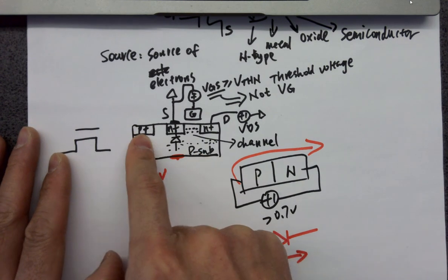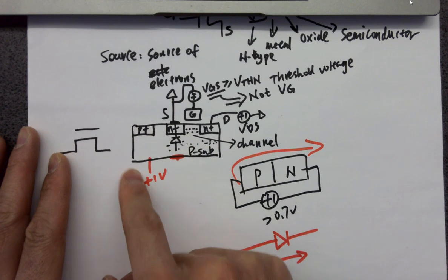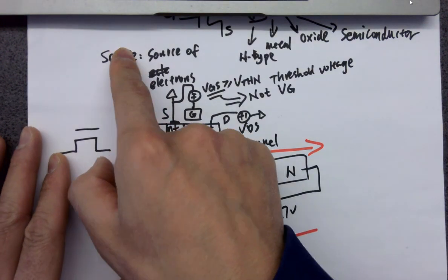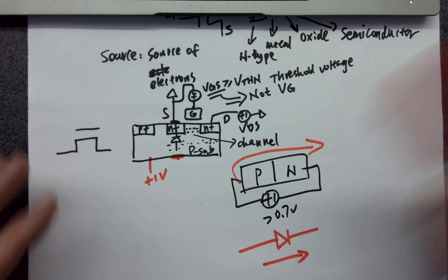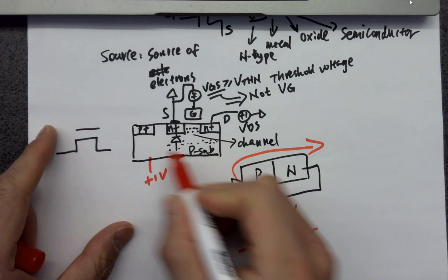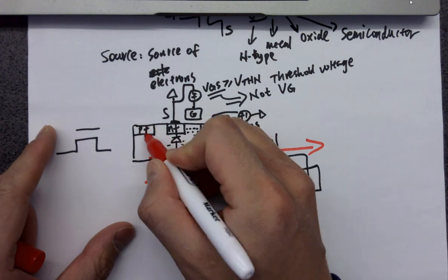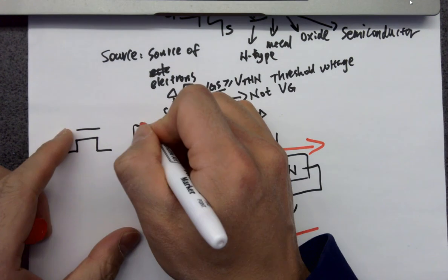We have to implant a P plus in the P-sub because everything is bottom up precise. So if you put a P plus in the P-sub, it's actually internally shorting to the P-sub, even though it's not exactly P plus, but they are both P-type. So they are shorted to each other. Okay. So in that case, you can have a via, right?